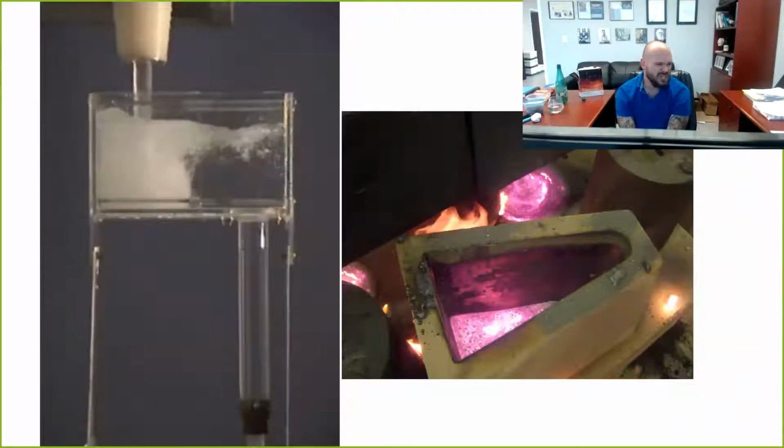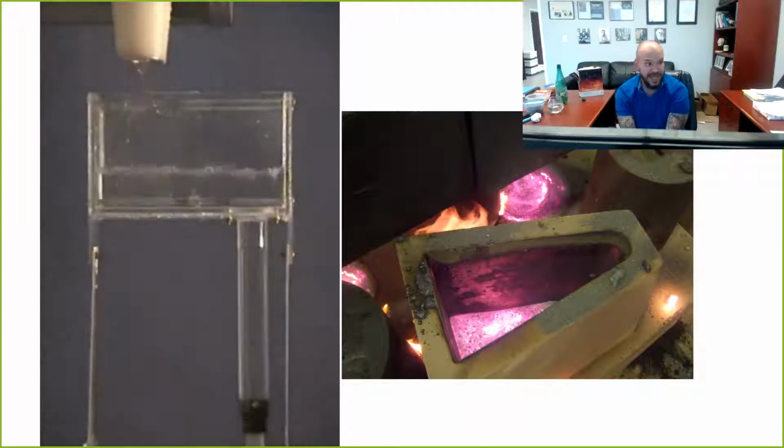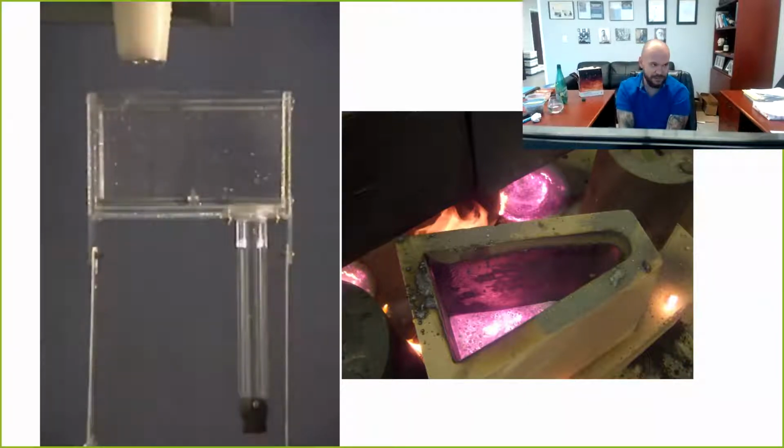Now we got a little bit of a choke, and this is straight sprue. So you can see that there's obviously flaws, but you can see what happens now is if we create a location where we can have a reduction or basically an elimination of that vertical velocity component, we provide an opportunity for the reduction of the aspiration mechanism. And now what we've taken it to is a prevention of the aspiration mechanism, which I'm going to show you next.